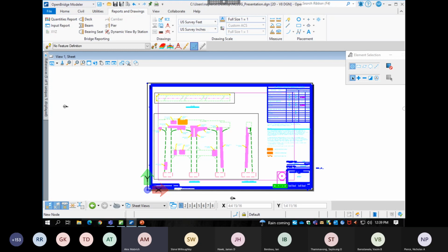That's why we said at this time use OpenRoads, because OpenRoads has all the tools, right? It has the linear template. Creating alignments is in OpenRoads and OpenBridge. Linear template is in OpenRoads and OpenBridge. But the target aliasing and benching stuff, or the template editor, because sometimes you want to edit that template, is only in OpenRoads. We're trying to port it into OpenBridge, so we're studying that option right now. Oh, great.